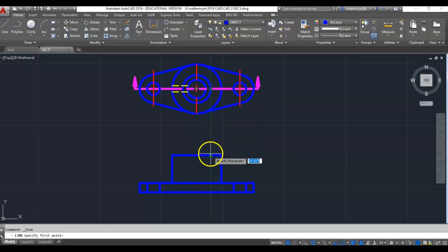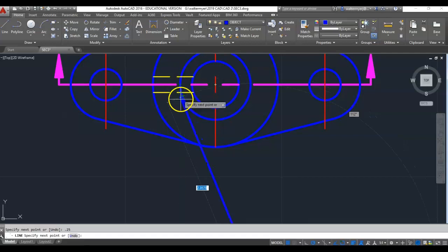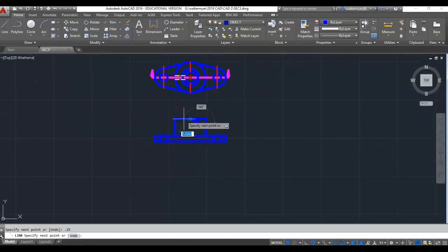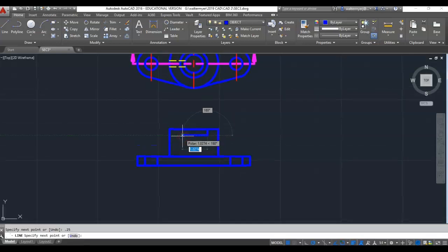Alright, the middle circle I'll bring down. Alright, that bigger diameter goes in 1/4 inch. 0.25. Bring the other side down. I'll just type her in. 1.125. Back up. Small circle. We'll go the rest of the way through. And then I'm also going to trim this flange that I wouldn't be able to see there anymore.